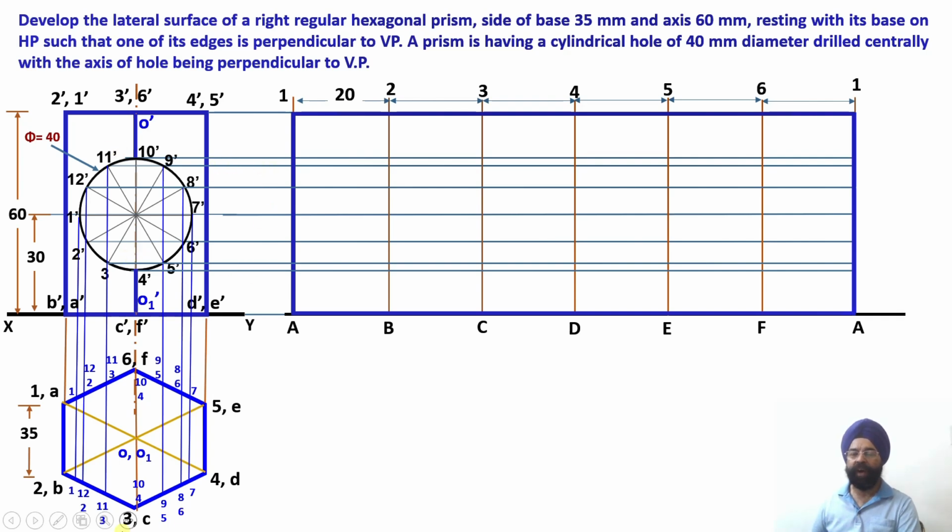But one thing I need to remember, because these points have to be located this way also: the height I have worked out based upon the front view, but the width, the distance of point 11 and 3, distance of point 12 and 2, distance of point 1 from point 3, these lengths I am going to get from the top view.